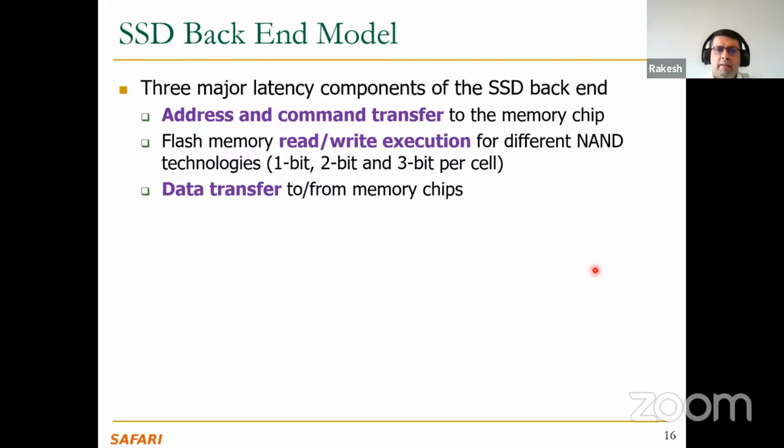Here we have 3 major latency components which have been modeled. One is the address and command transfer to the memory chip. And then we have the execution time of the flash read and write operations for different NAND technologies. It could be 1 bit per cell, 2 bit per cell, or 3 bit, which is SLC, MLC, and TLC. And MQSim also models the data transfer from the controller to the memory chips, and also back to